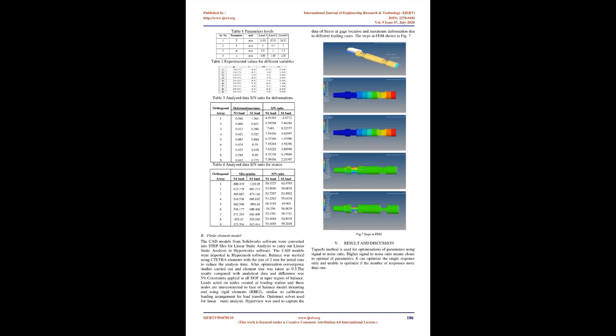4 active strain gauges were used to measure each component of the balance in the Wheatstone bridge circuit. The sectional view of yawing section and pitching section is shown in Fig. 5, and the equations for bending stress are derived using the bending moment equations. Therefore, bending stress at gauge location for normal force measuring element is given by equation 2, where P, L, M, and N are the sectional dimensions of the lift force and side force measuring element as shown in Fig. 5.